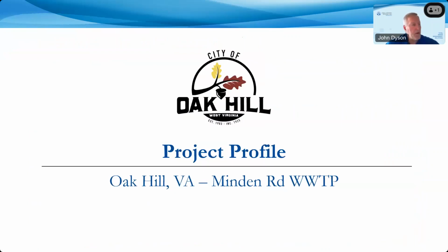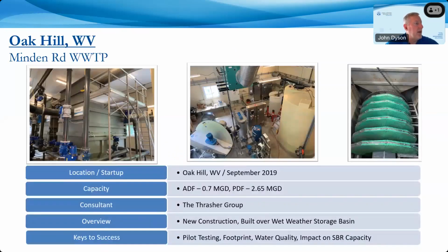I'm going to talk about one of the older projects that we have, the Oak Hill facility, called the Minden Road facility. This was an existing SBR facility with an average day flow of about 0.5 to 0.6 MGD. They needed to expand the capacity and increase their average day flow because they were bringing in additional flows from a neighboring town. So they had to take their old SBR system from 1.6 up to as high as they could get it.